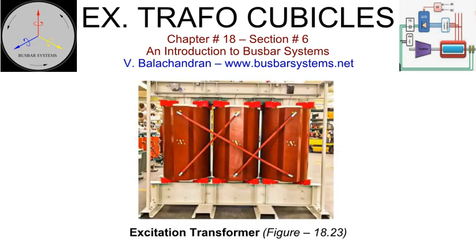Excitation transformer. The 3-limb transformer has independent primary and secondary windings that are individually cast. The high voltage and low voltage coil assembly has air as the primary insulation. This air column also acts as a cooling duct with natural or forced air cooling. The primary coils are connected in delta and the secondary in star. Cooling fans are installed at the bottom of the coils.